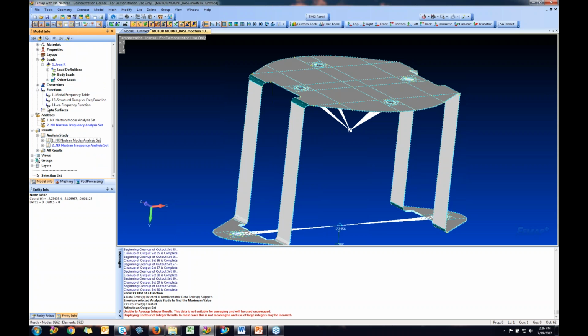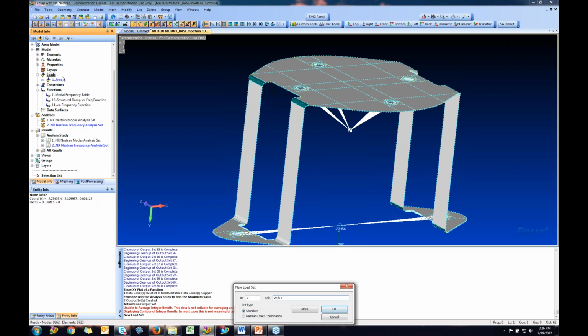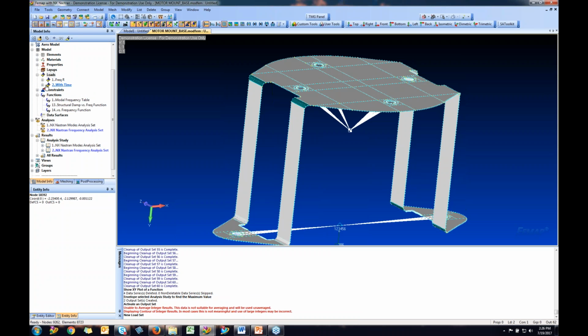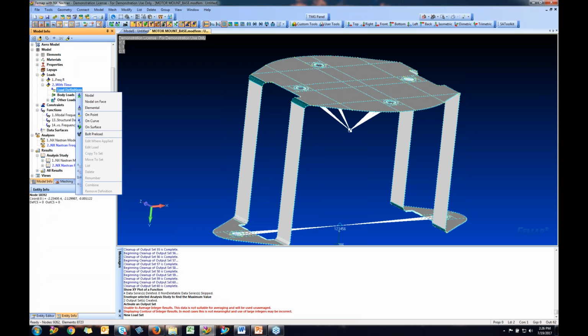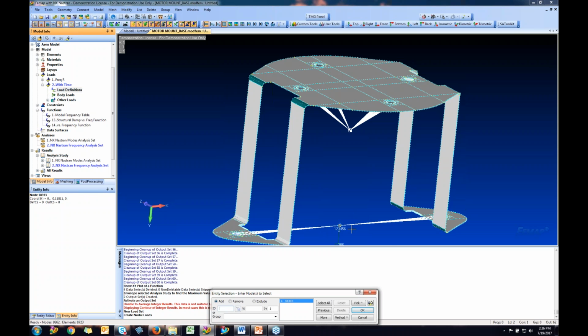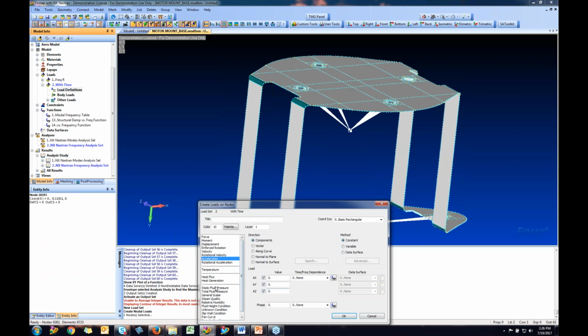All right, so let's hop over to a quick transient analysis. For this, I need to create a new load, and this is with time, since we're hopping into transient. Our load definition, I'll say nodal, and I'll apply it to that same location. This time I'm going to apply a displacement in the y direction, let me give me 1 times some sort of frequency dependent, this time it's time dependent function.